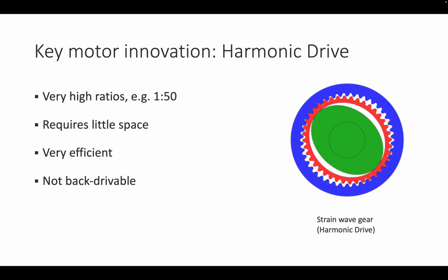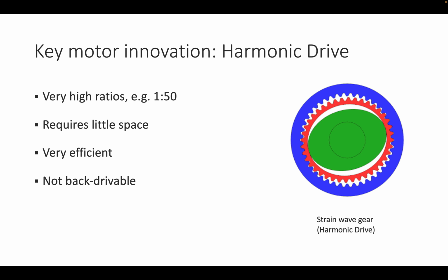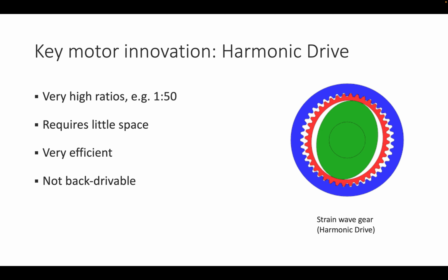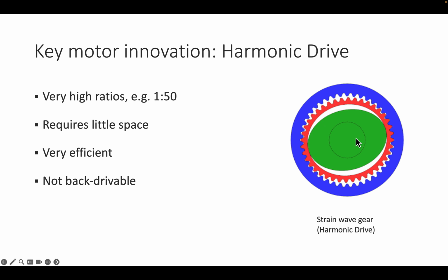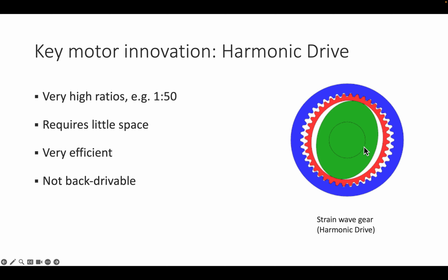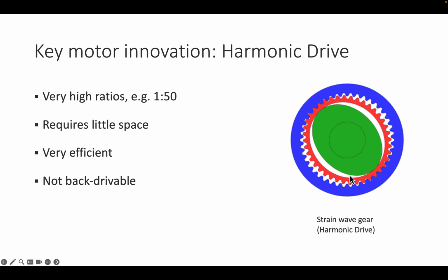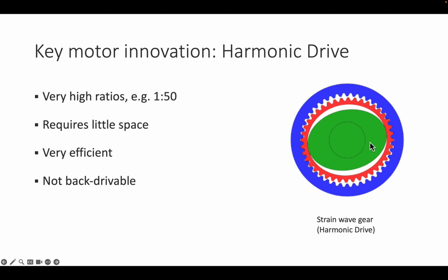Another component you will need is the gear reduction, and here the key motor innovation in the last few decades has been the so-called harmonic drive. The harmonic drive is a very sophisticated mechanical device in which you can achieve very high gear reductions using very little space.